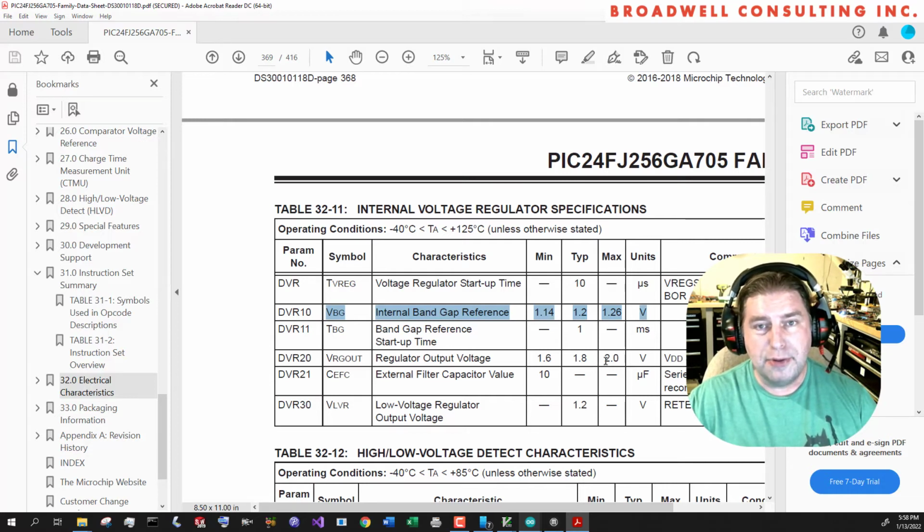Again, not a perfect way to measure a resistance, but pretty awesome if you want to tell the difference between a high resistance and low resistance, as we do with the address pins, or do some other operation where you want to tell qualitative resistance ranges as opposed to perhaps a precise value.